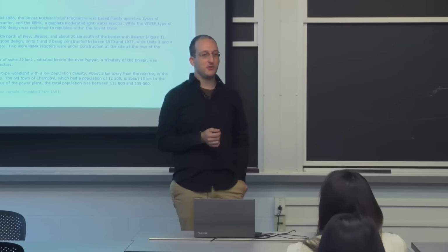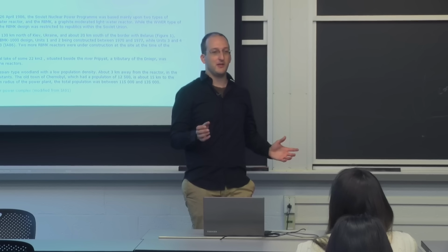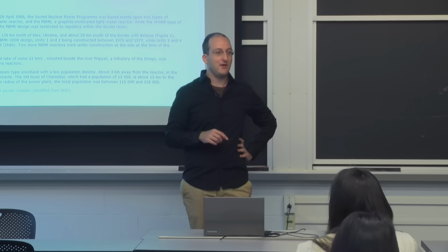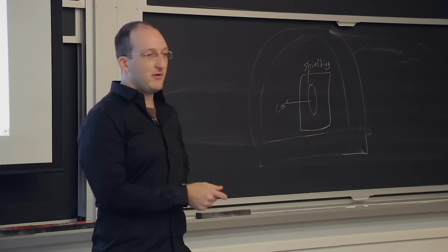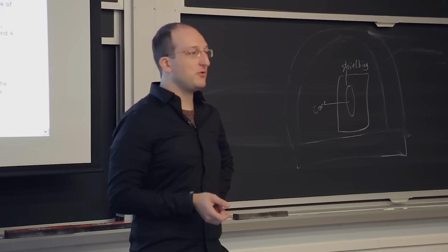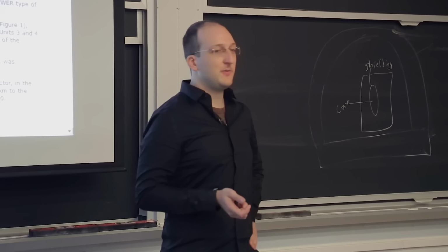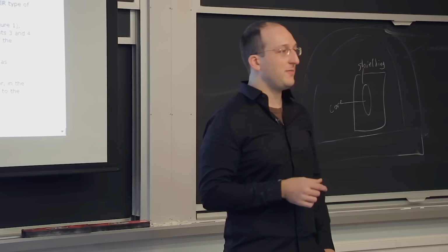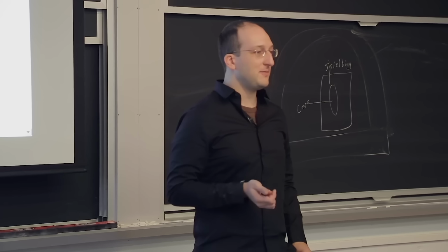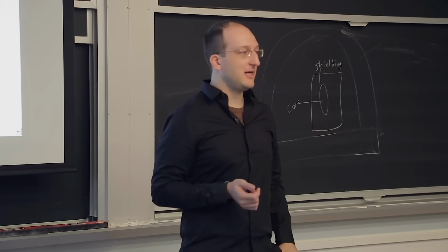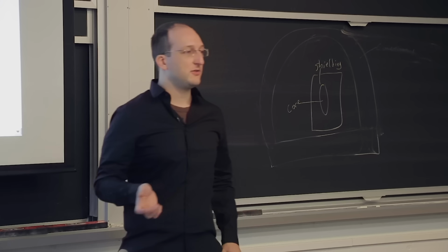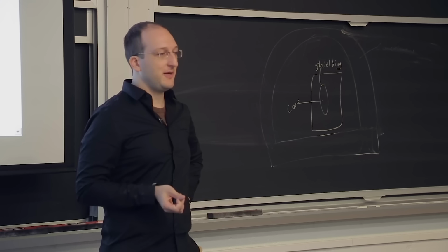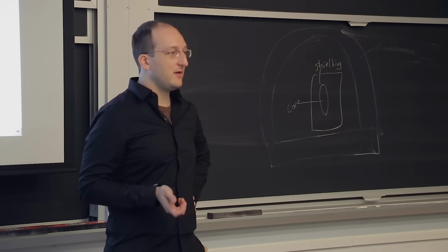But the turbine, like I showed you a couple weeks ago, is this enormous spinning hulk of metal and machinery that coasts down over a long period of, let's say, hours. And as it's spinning, the generator coils are still spinning and still producing electricity, or they could be. So it was desired to find out, can we use the spinning down turbine to power the emergency equipment if we lose offsite power? So they had to simulate this event. So what they actually decided to do is coast down the reactor to a moderate power level, or very low power, and see what comes out of the turbine itself, or out of the generator, rather.